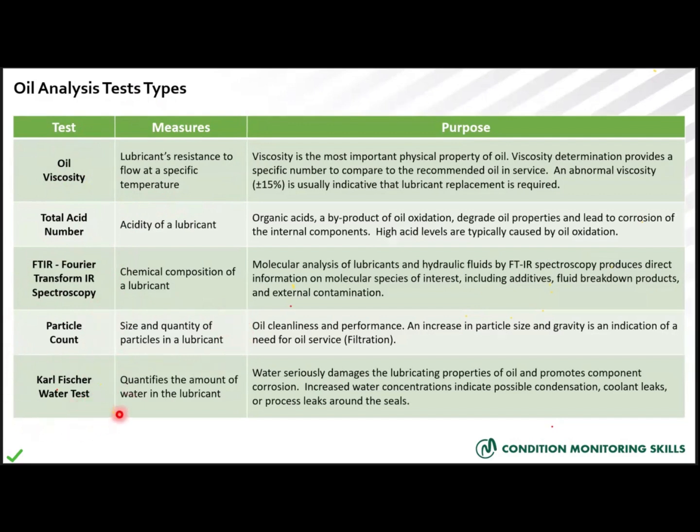We can do the very famous Karl Fischer test, or the water test, to know the water content in the lubricant. Each one of them measures a specific property, a specific thing we need to know, or maybe a specific issue we need to know about the oil or the machine, and each one has its own purpose.